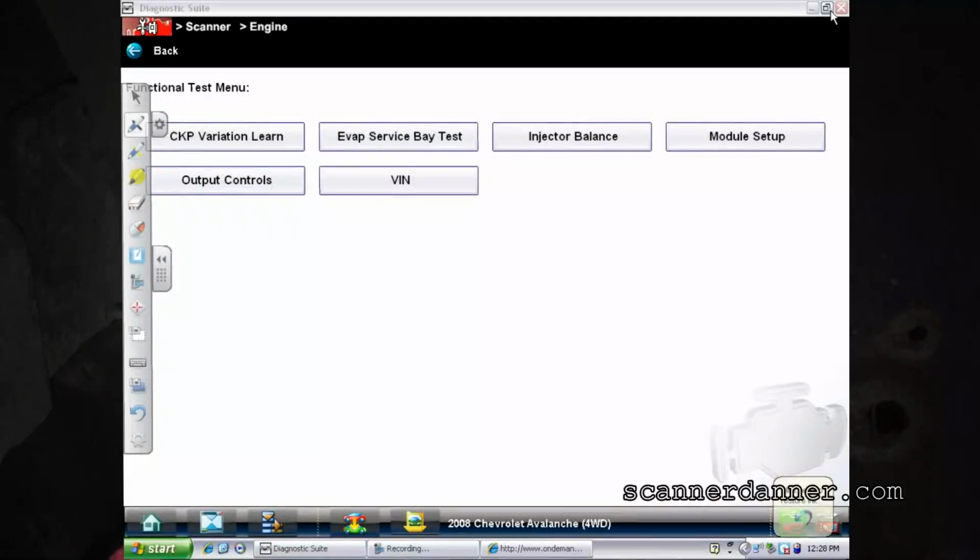Questions? All right, that's pretty much good for this. Again, that's section 3, ground side switch circuit. We tested the solenoid, we tested the driver, we tested the control circuit. Used the test light to confirm the driver circuit integrity. A manufacturer flowchart would have you disconnecting the computer, disconnecting the solenoid, and doing resistance checks. You'd be there all day.